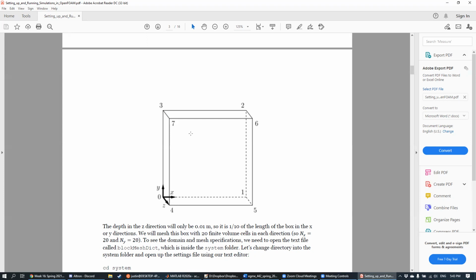I think you'll understand the reason: if you compare your code for a 1D problem versus a 2D problem, some of the principles are still applicable, but they look like very different codes, because the formulation in 1D looks very different from the formulation in 2D. So OpenFOAM said, because we'd have to write a whole new code for a 2D problem, let's not do that and just write a 3D code, then make some modifications for people who want to run 2D simulations. Just keep in mind that we're working with a 3-dimensional geometry, but we're going to treat it like it's 2D.